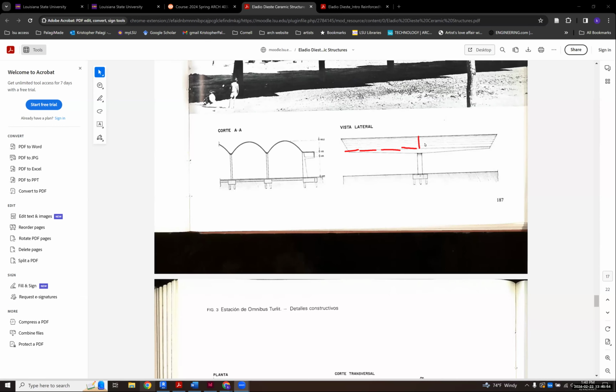Okay, so that was just something we kind of came in as a rule of thumb that we're using, because really that's the depth of the beams that are cantilevering out, right? A lot of times we think of just a simple vault. If this was a wall here and a wall here the whole way, then it would just be about the vault spanning from here to here, and its depth would really affect how much outward thrust would be happening on those walls as if it's just coming down.